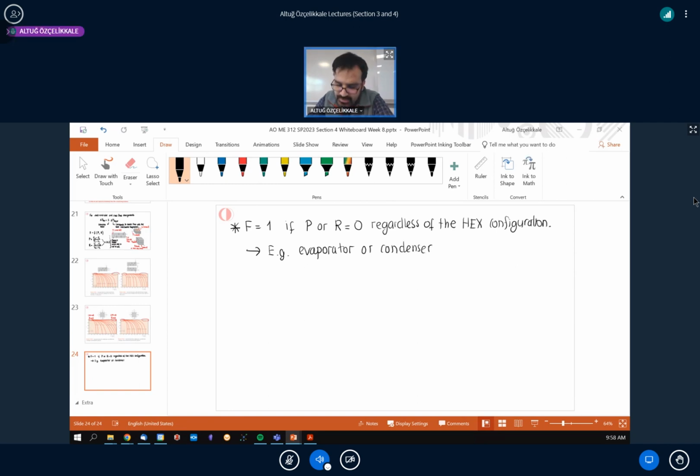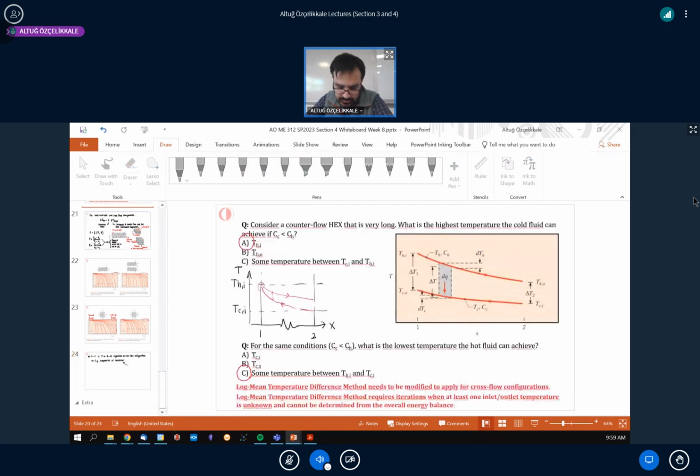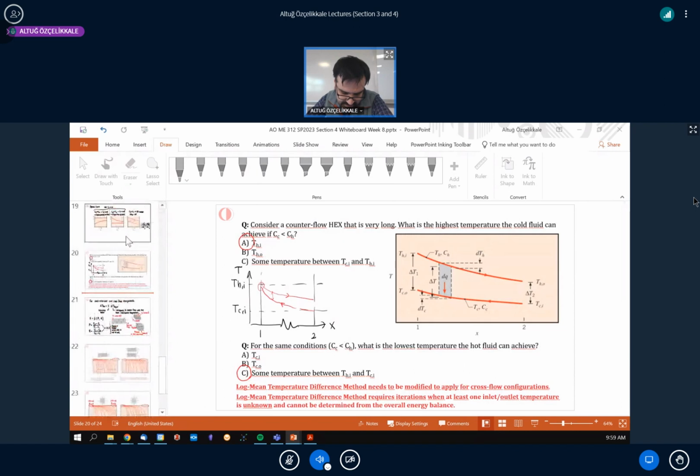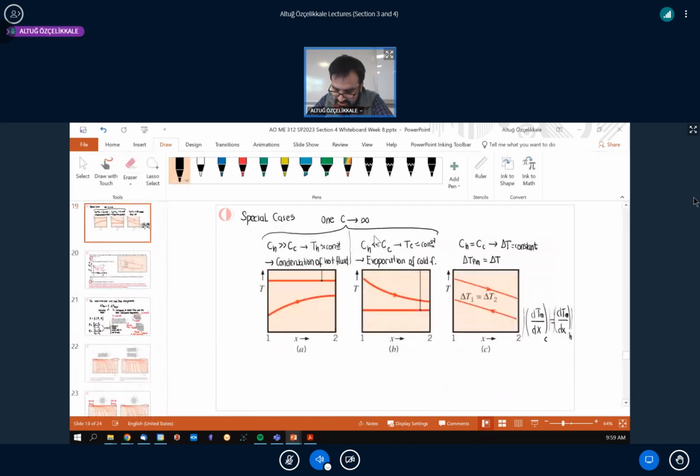It is helpful to remember the special case with the evaporators and condensers, because remember that in the case of log mean temperature difference, we also discussed that special case because we based our analysis on sensible heat effects. So consideration of latent heat effects actually falls outside the log mean temperature difference analysis. So that's actually saying T going to infinity, we are actually approximating phase change behavior, but that's not exactly true, right?